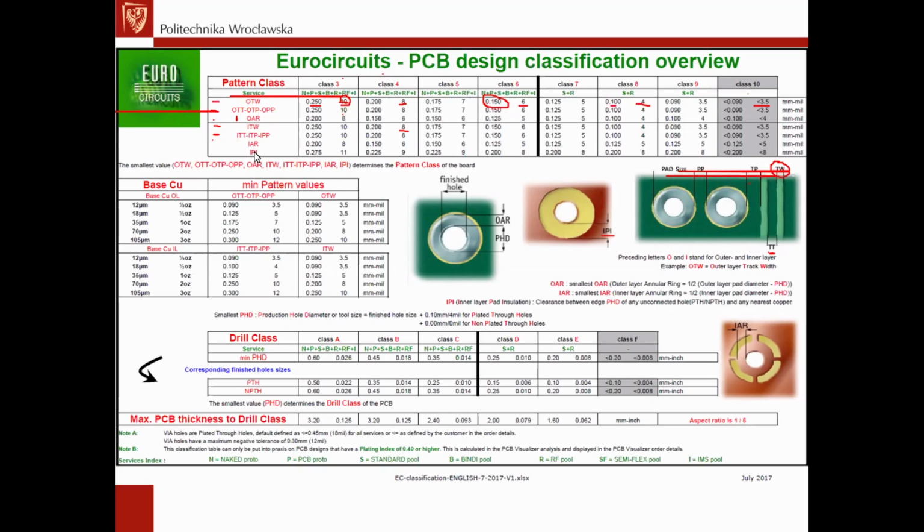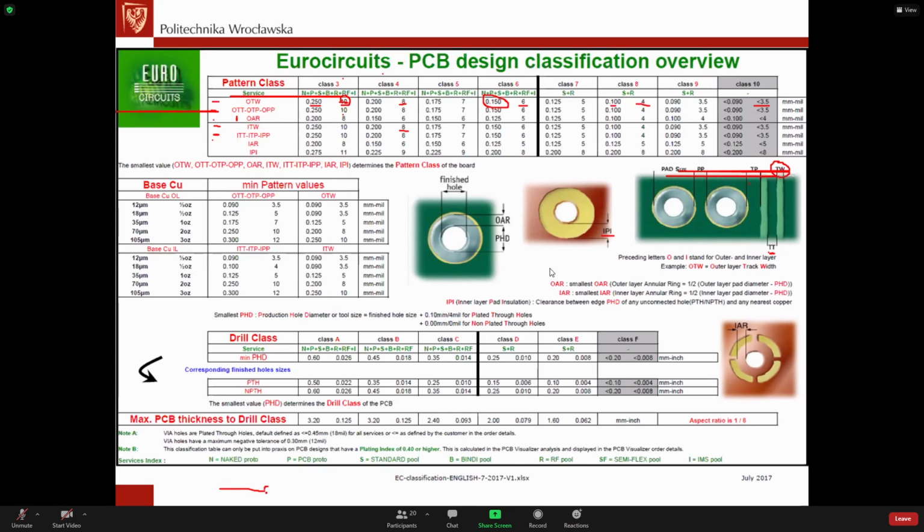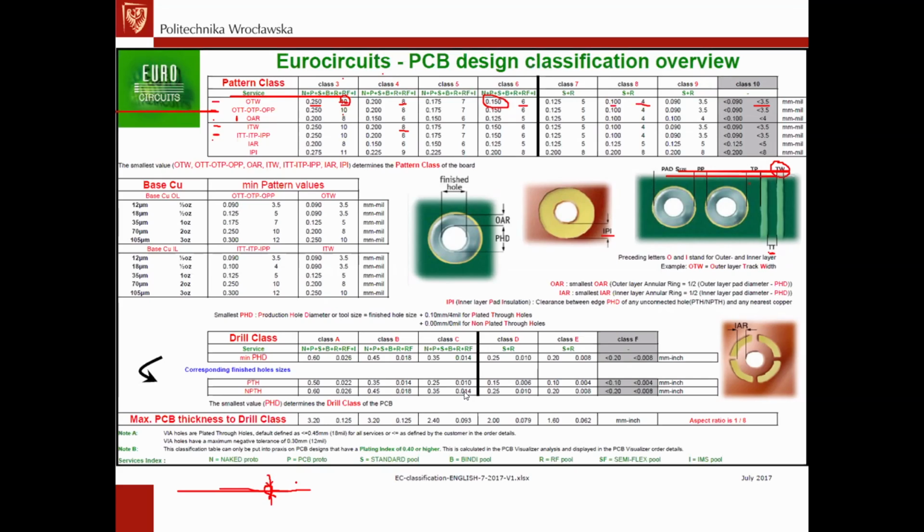This time, considering all the holes we have in a PCB, so the vias and the paths, especially the vias, connecting two tracks are of very much importance because of the high number of them on the board, and because of their size, because they occupy more than a track. Remember that normally we have a pad on the top layer, a track on the top layer, a via, and a track on the bottom layer. And the diameter of the via is always larger than the thickness of the track.